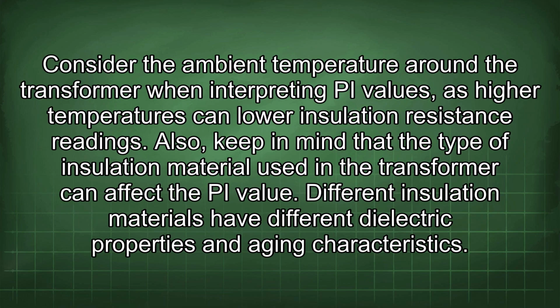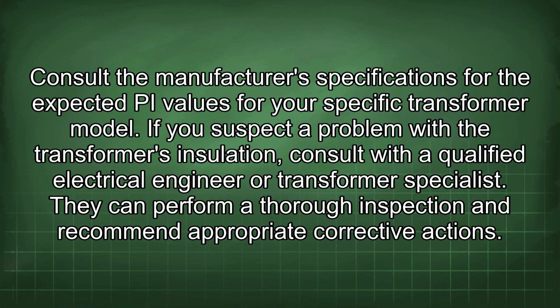Consider the ambient temperature around the transformer when interpreting PI values, as high temperatures can lower insulation resistance readings. Also, keep in mind that the type of insulation material used in the transformer can affect the PI value. Different insulation materials have different dielectric properties and aging characteristics. Consult the manufacturer's specifications for the expected PI values for your specific transformer model.